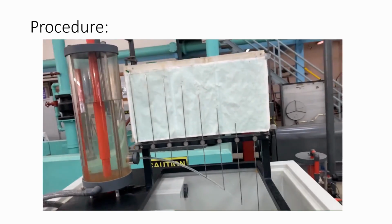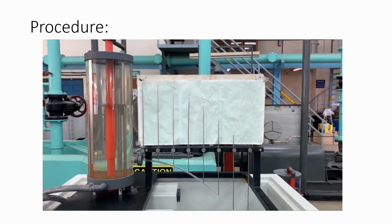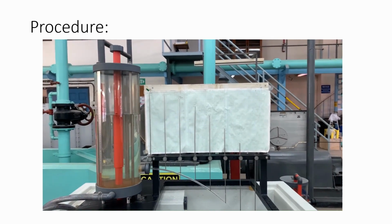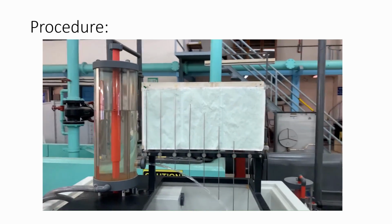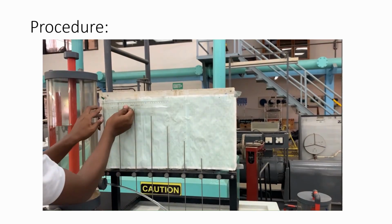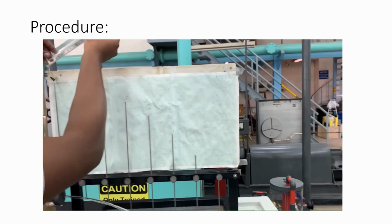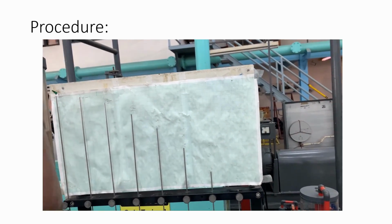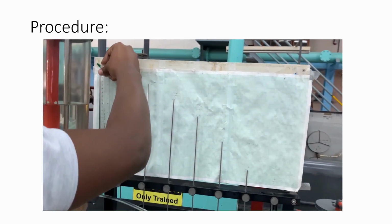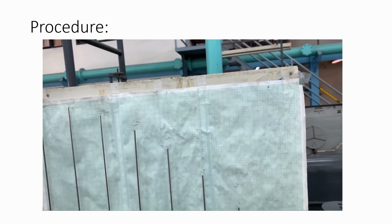We then go on to the next step where we measure and record the X positions and the Y positions. Here we see we're recording the distances between the probes. The distance is the same between all the probes. Now we are measuring the y positions. What was recorded previously was the x distances. Now we are measuring the y distances.